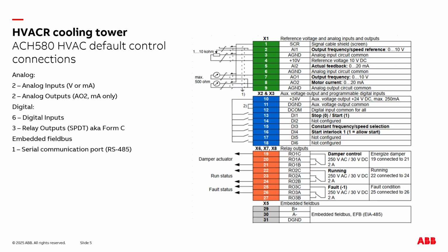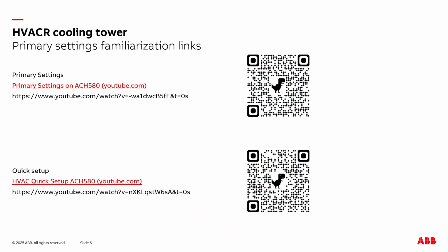Now, after I introduce each lab and the programming requirements that need to be done on the drive, I'm going to take a second and pause and allow you a chance to program the drive first before I show you how to do it so you can hopefully learn. Now, if you're a little lost in saying, where do I go? How do I start? I'm not familiar with the ACH580 drive. Here are 2 big hints. Most of the programming I will be doing in the drive is going to be done in primary settings and even a submenu of primary settings called Quick Setup. So if you're not familiar with these 2 features in a drive, I recommend that you watch these 2 videos first before going on with the labs.